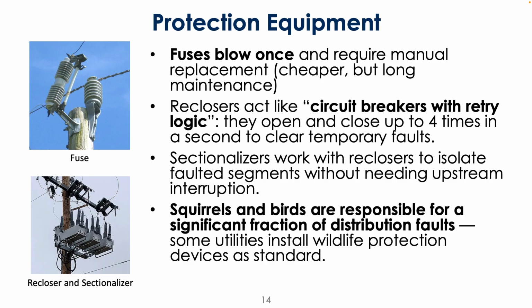If I make sure I don't have sag in the lines as they start to degrade, then even in higher wind events they're not blowing into things. But with wildlife, unless you exterminate the squirrel population, you're not really going to be able to solve all of these issues.